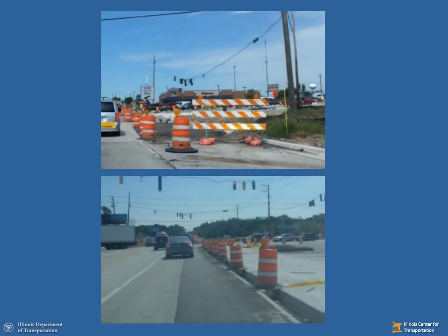Here are some photos of some traffic control that we might need surveillance for. Here we've got missing pavement, we're reconstructing, and these vehicles are definitely within 8 feet of that open lane. Same thing down here. Here I've got the gap between the old pavement and the new reconstruction. Definitely is a hazard within 8 feet of an open lane. Anything on these pictures that doesn't look right to you?